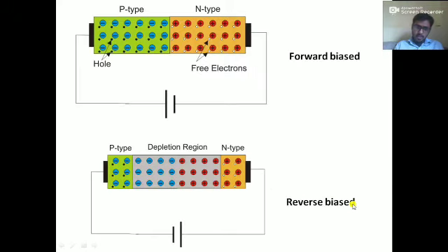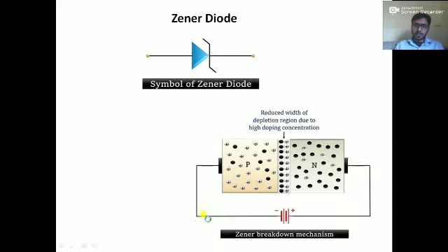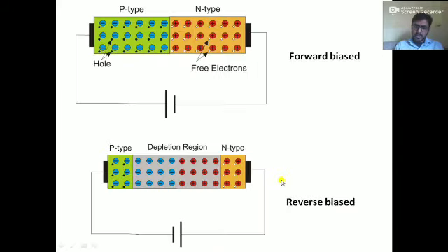But if I am talking about this type of junction, a reverse biased normal diode, the electron is accelerated when you increase the field, but the depletion width is very large compared to the depletion width of the Zener diode. So this electron gets accelerated and moves with very high speed, and it collides with some of the silicon atoms present inside this area.